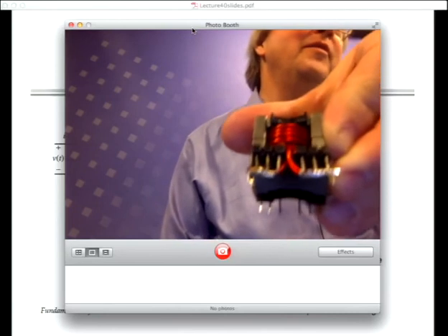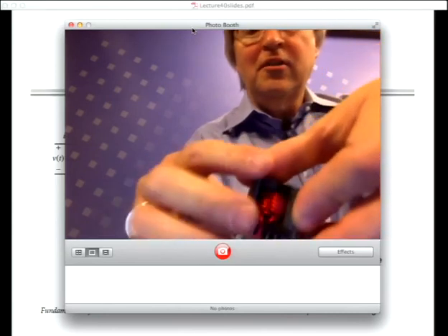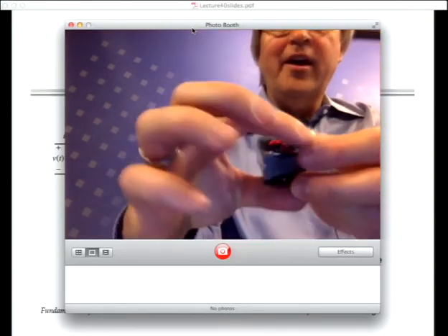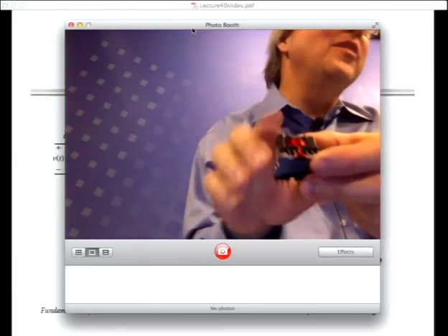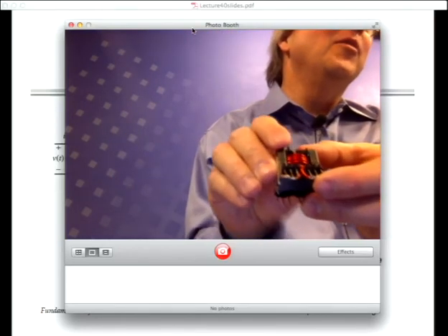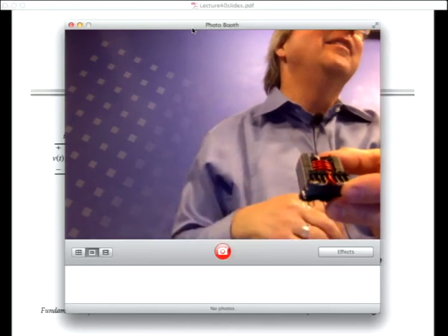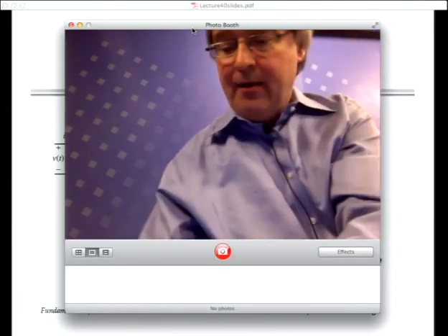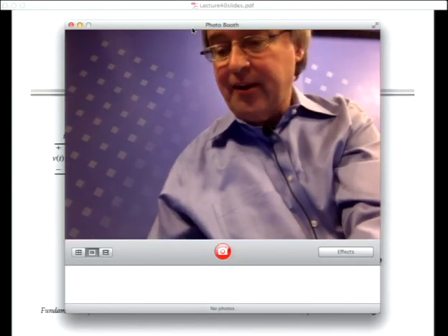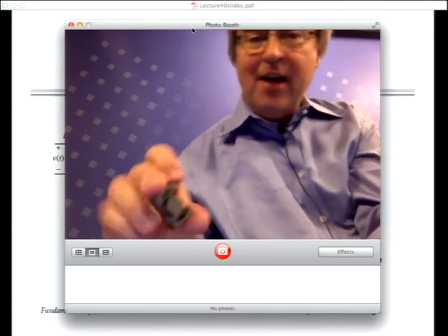printed circuit board. The PQ cores have a square bottom, so they take up a square piece of real estate on the printed circuit board. And the whole core is shaped around that to try to minimize the amount of printed circuit board area. And the other thing that they have that's a nice thing is that they have a round center post.